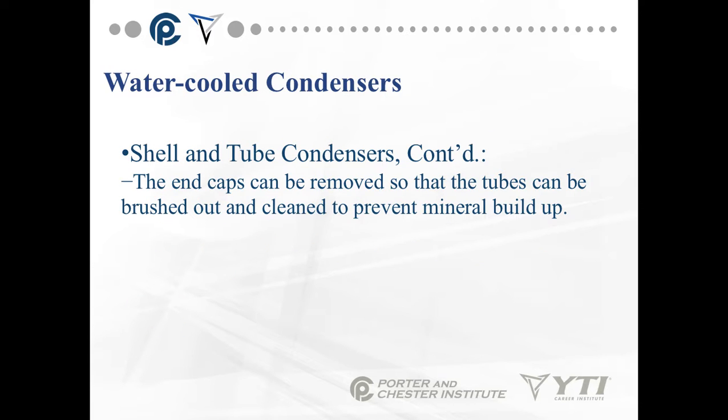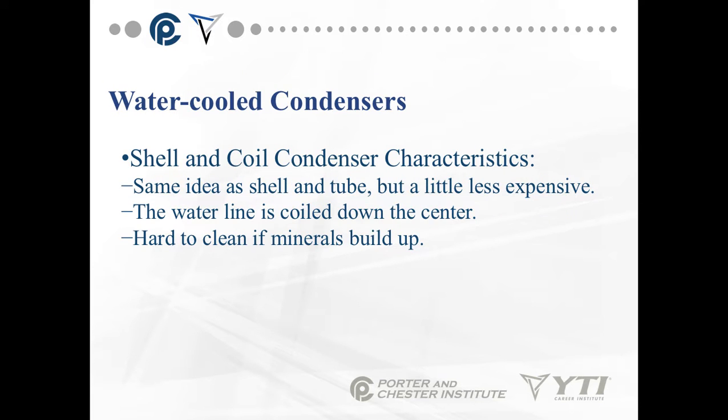The end caps of all of these can be removed so that tubes can be brushed out and cleaned to prevent mineral buildup. Again, mineral buildup is a pretty major issue with water-cooled condensers. Water does have minerals in it, and it will eventually start building up on metal and cause blockages.